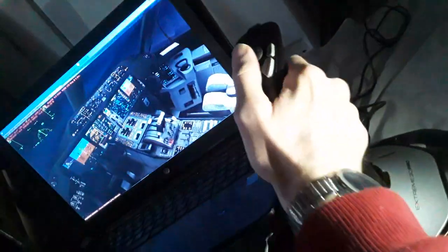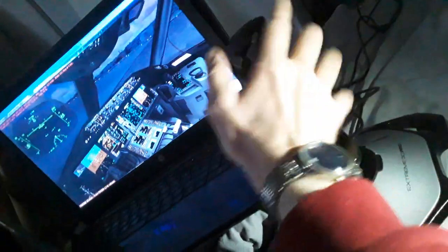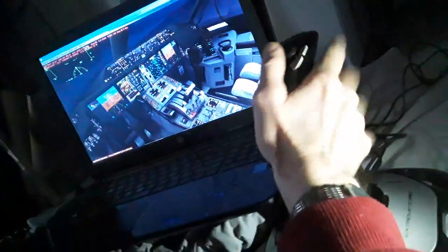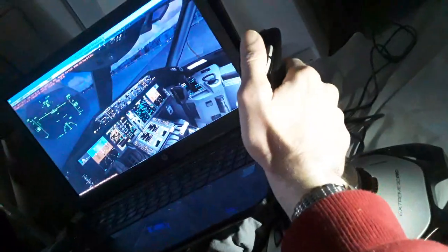So we can use also, you can see the side stick again. You see the side stick deflection is proportional to the yoke deflection. Also both sides, the captain and the first officer in the Boeing, all flight controls move together. Unless you have a failure, use the override force from either side to control the Boeing flight controls.